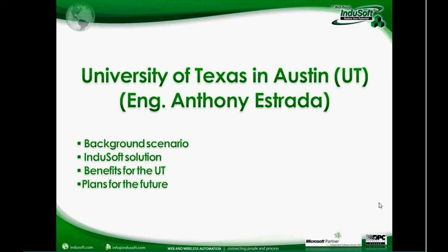And the camera manufacturer provides an ActiveX control or .NET control that can be easily integrated to InduSoft Web Studio to display live images from the cameras. And depending on the features provided by the camera manufacturer, you can even pan, tilt, or zoom the camera from InduSoft Web Studio. So the answer is yes. You can display live images from InduSoft.